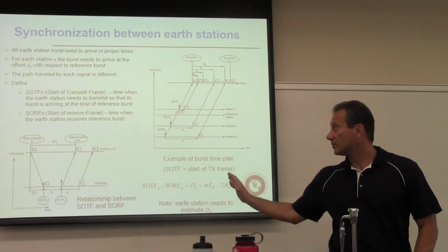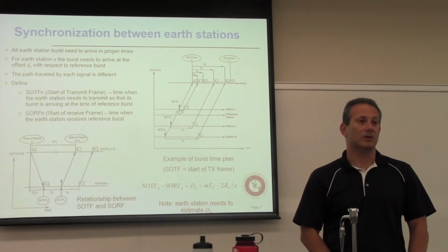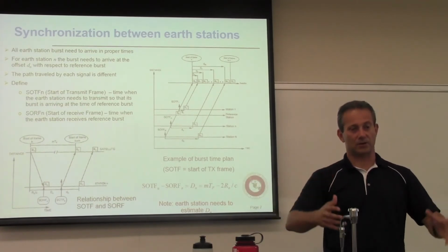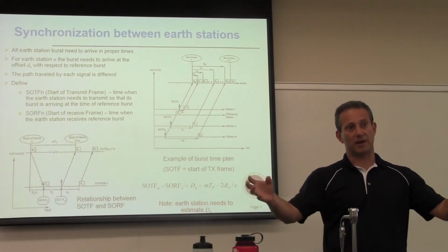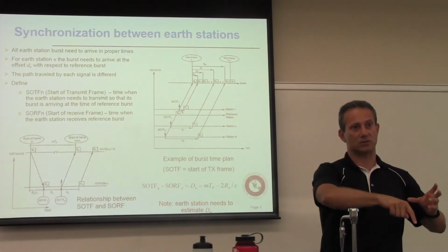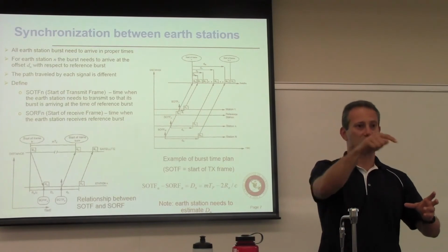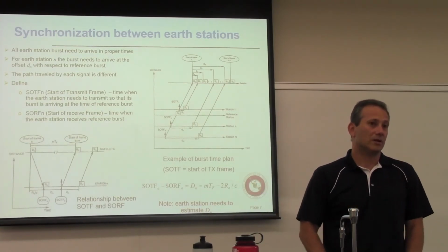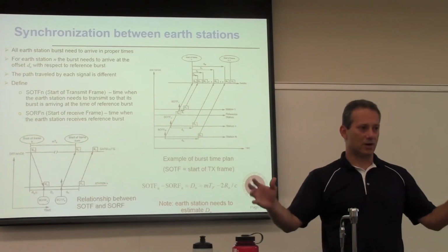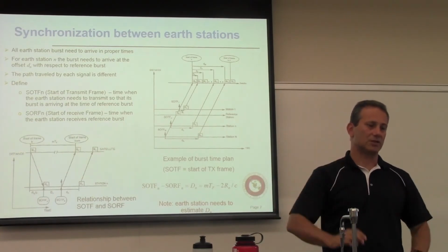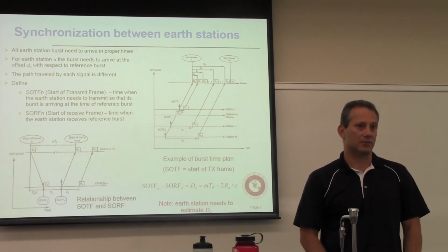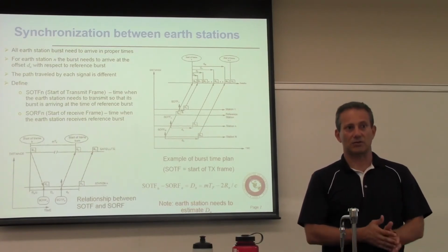But a lot of these networks are actually set up manually, right? You have a network with a high-powered earth station that you bring up manually, and you say, you guys use this time slot, you use that time slot, because this is all in a backhaul. Remember, TDMA is usually used for large earth stations that are sending a lot of data. So you set this all up and then you just operate the network. Dynamic access is not very common here.